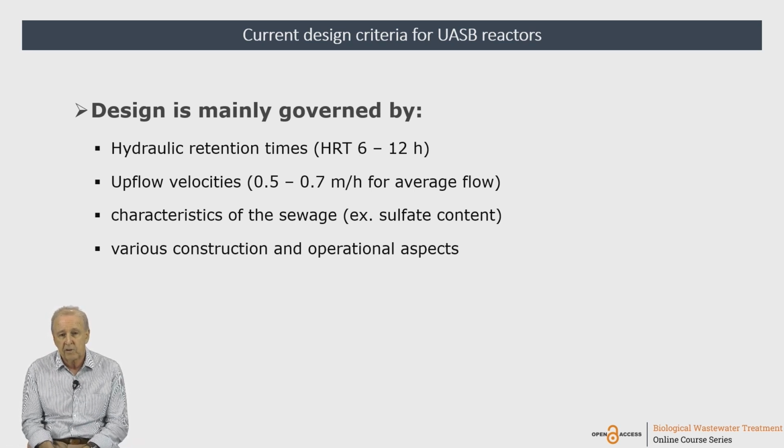As domestic sewage is usually characterized as a low concentration effluent, with BOD around 250, 300 milligrams per liter, and COD around 500, 600 milligrams per liter. We know that in some countries, like Jordan, Julius has called attention to this in many previous lectures.